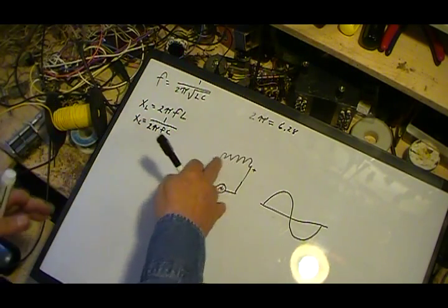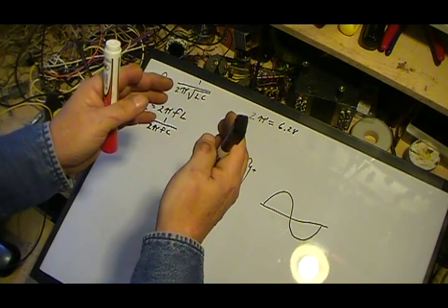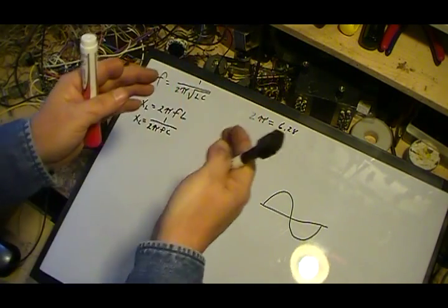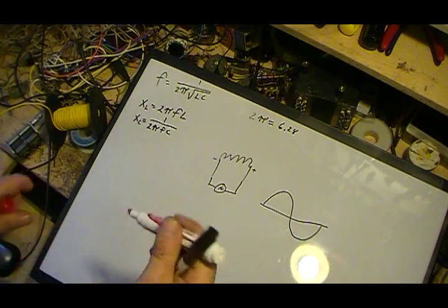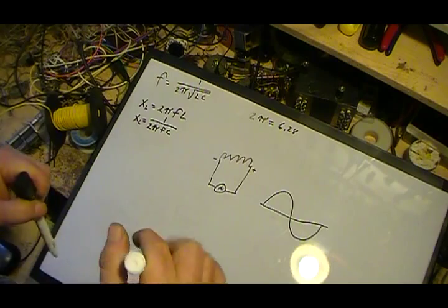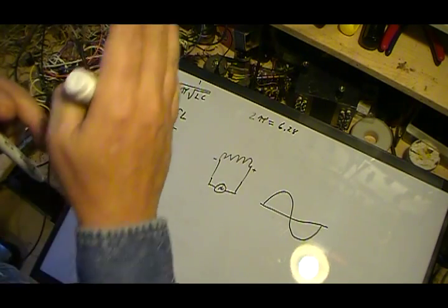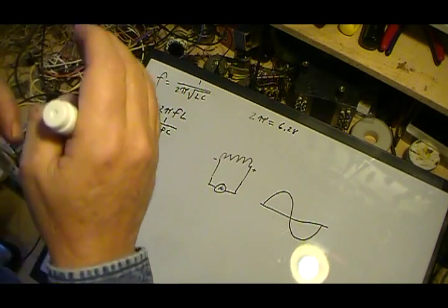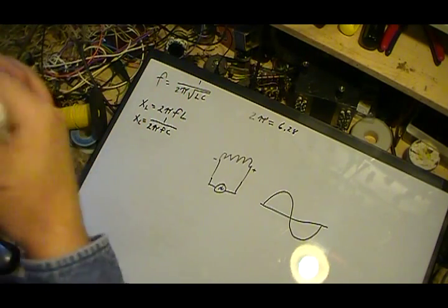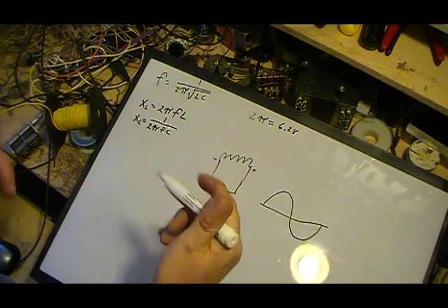As it expands, it cuts across the wires in the coil. In turn, that induces what they call a counter EMF, or counter voltage, because the field is moving with respect to the wires, but it's producing a voltage in the opposite direction because of the way it's moving.